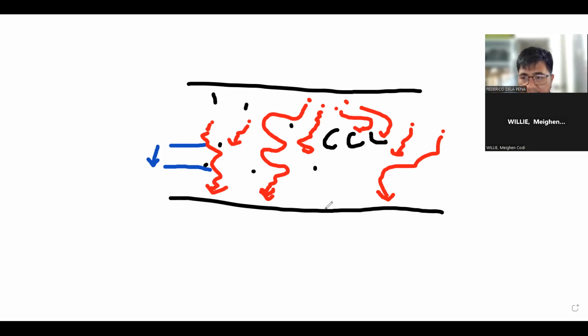And that would still be a concern in terms of contamination. And that is what you would want to know. What is the earliest time in which the leachates would arrive at the bottom of the CCL? And you can determine that by using the seepage velocity, not the Darcy velocity.